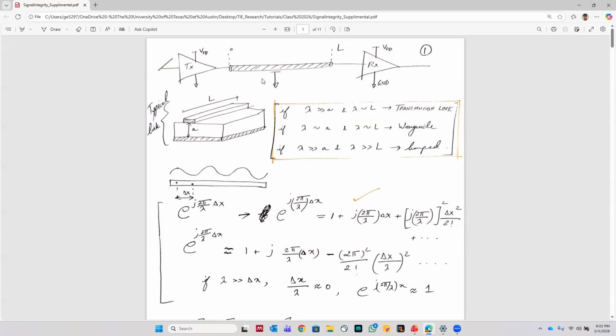Yeah. Okay, so basically what we talked about was the fact that as chips are scaling because of Moore's law scaling, the number of terminals coming out of the chip is basically increasing. However, the package is not scaling sufficiently. So you have a limited number of channels on the package, but you have a lot more terminals coming out of the chip. And therefore, the only way to use the minimal channels on the package to communicate between two chips is to basically take parallel terminals and convert them into a single serial terminal using something called a SerDes.